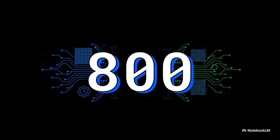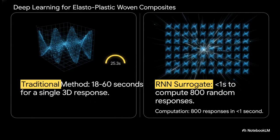Beyond just accuracy, we absolutely have to talk about efficiency. And the magic number here is 800. So the crucial point is this. The original mean field simulation requires anywhere from 18 to 60 seconds just to compute a single 3D loading response. But the fine-tuned LSTM neural network takes less than 1 single second to compute that exact same response for 800 random test sets. It is a staggering, massive computational upgrade.